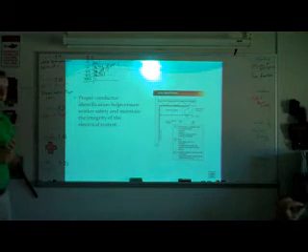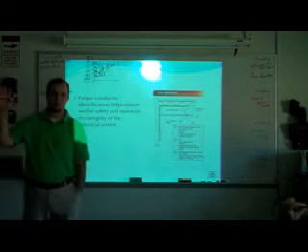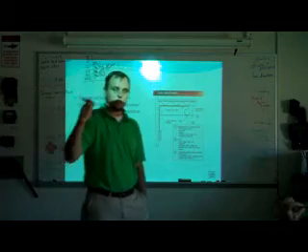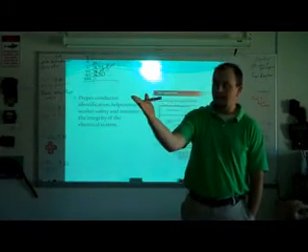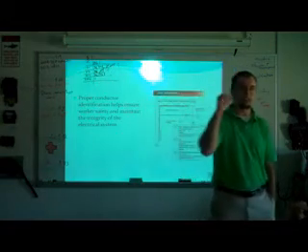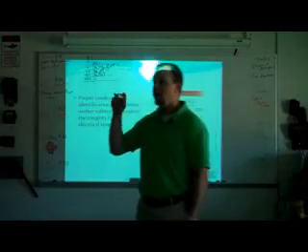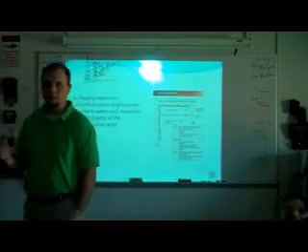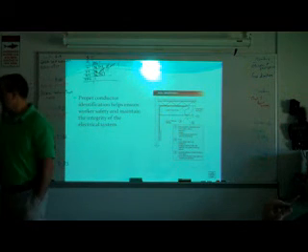So that's why, when we were pulling our wires through the conduit, we were all using different colors. That way, if Zach's lab failed, we know that he's on the pink wire, so we can follow the pink wire easily. We know that the pink wire is the hot wire, the white was the neutral, and the green was his ground. It just makes it that much easier.